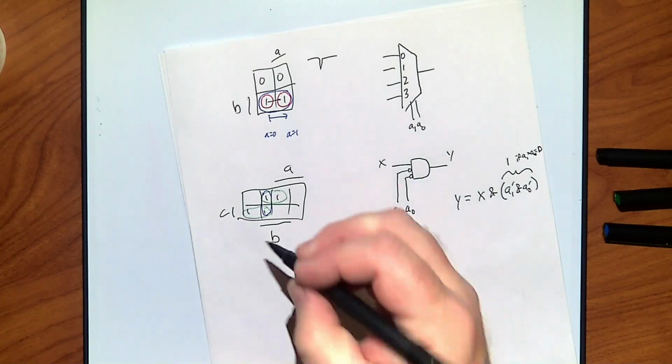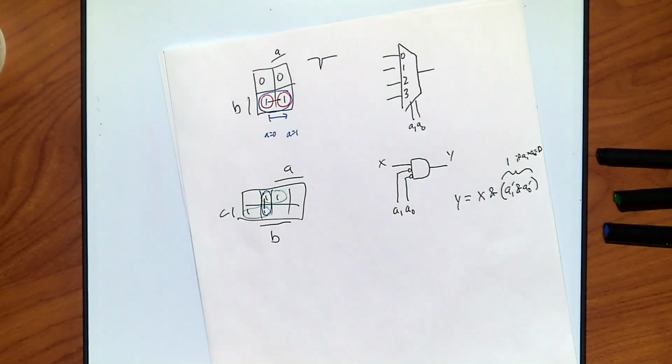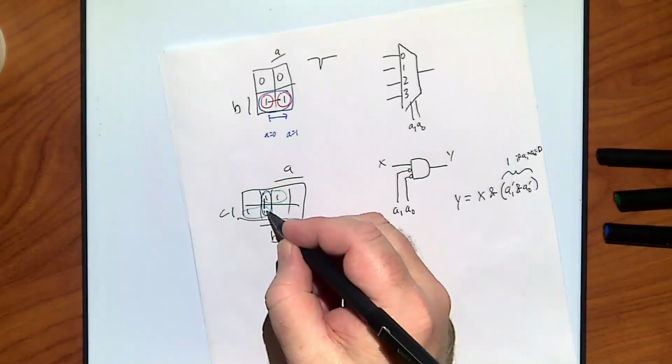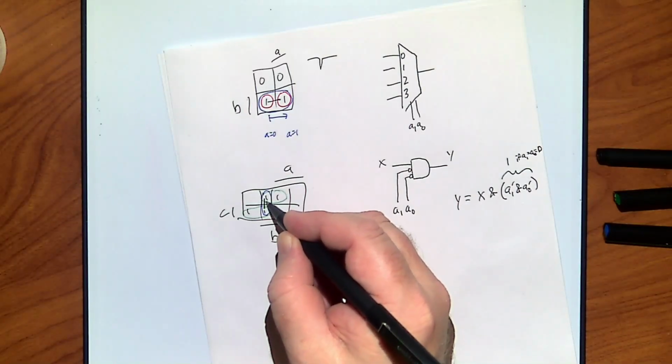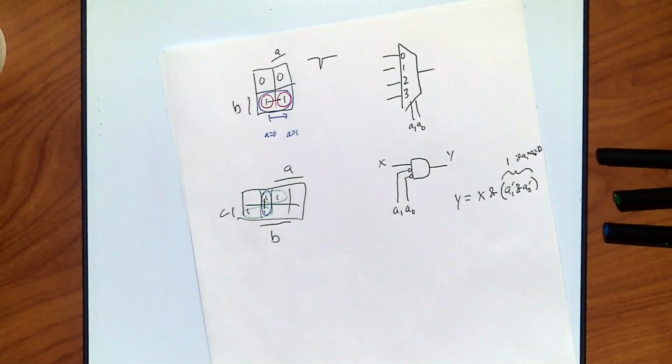The reason is if you don't, when you do this transition here, you are going to go from green on to both off to the other green on. Whereas if you have the blue, there's something maintaining it staying on, so you don't get that momentary drop in between.